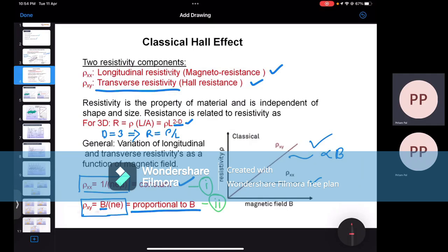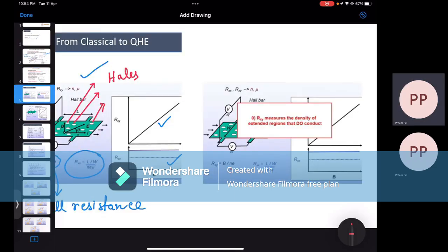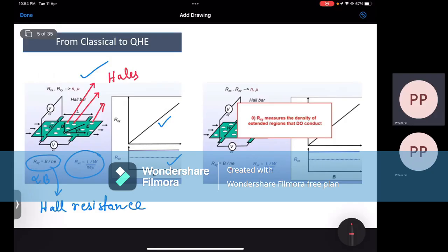This is our longitudinal resistance, rho L by A. Keep in mind this formula, because it is going to answer these questions. The current goes through an effective narrower width, which means that my longitudinal resistance will go up, because this W actually goes down.